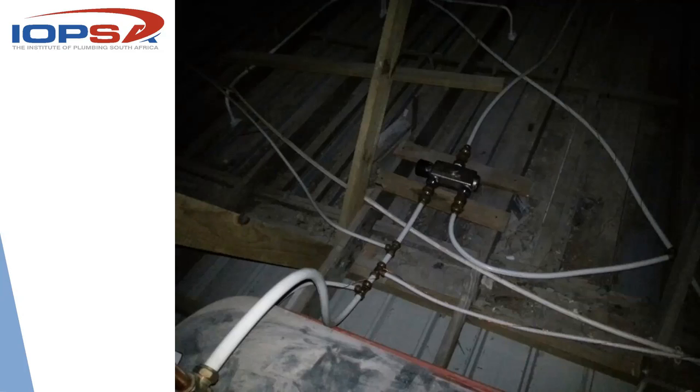And if it's not secured, that's also a pipe that meanders along like a windy path. There is friction loss there that's going to occur. It's unnecessary. It's a waste of pipe. It's untidy. And so, all these reasons for bracketry. Now, we will get to the table detailing what the distances are for water pipes and plastic pipes in particular.